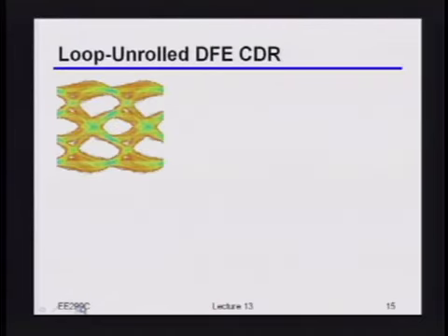Okay, so in case you thought we were done, there's still a little bit more fun to be had in CDRs. I guess nobody this time around did it, maybe because I banged your heads on how annoying it was to adapt these things. But nonetheless, loop unrolled DFEs are still fairly common and popular out there in the real world, so to speak. If you do a loop unrolled DFE, then your life is fun not just because of adapting the actual value of the coefficients for the DFE cancellation itself, but it has some pretty direct implications on the clock and data recovery as well.